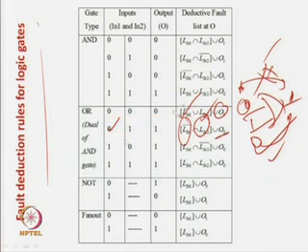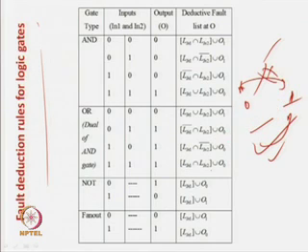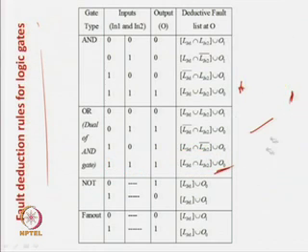Similarly, you can find out the rule for 1 0, which is this one, and 1 1. In this case it is just like 0 0 for the AND gate: nothing gets propagated excepting if there is a common fault for both of them, and for 1 1 the answer is a 1. So, in the output case a stuck-at-0 fault will be detected. That is what is stated over here in the table.